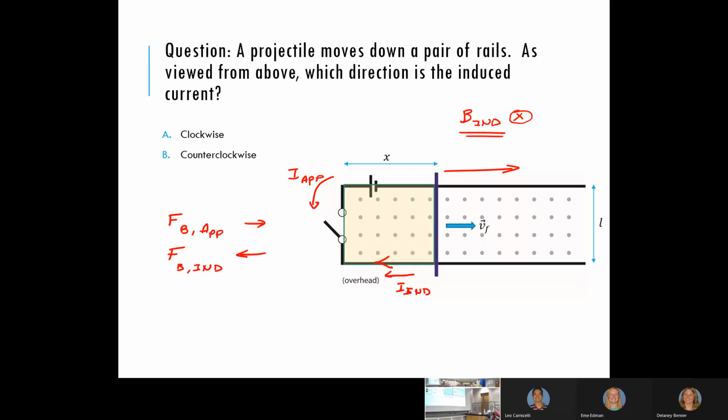If we go back to this railgun idea, the chamber is long enough so that you can get the projectile up to a high speed. But there is some optimal length. If they make it any longer, that won't actually speed up the projectile. So there's an optimization thing. If we get it too long, then the induced current will end up equaling the applied current, and then the object won't accelerate any further. So there's no added benefit to making the railgun 50 miles long. So my guess is that they've optimized it.